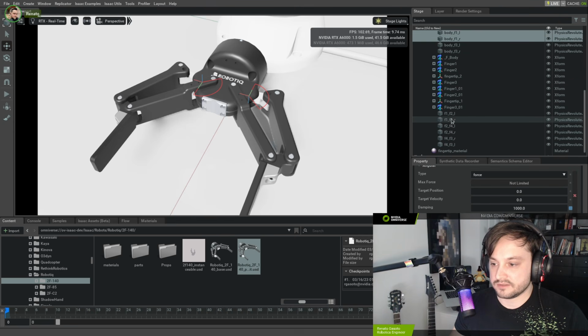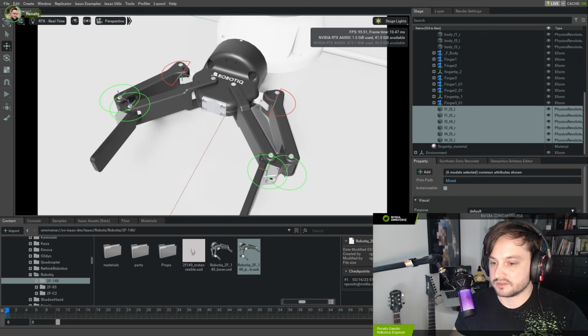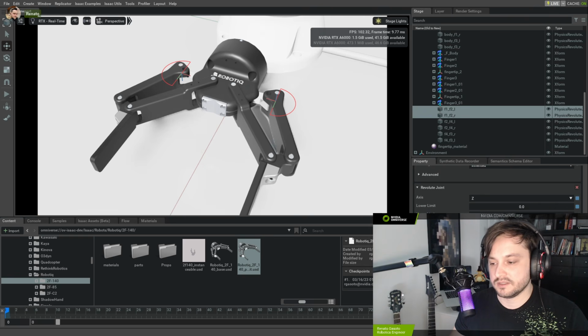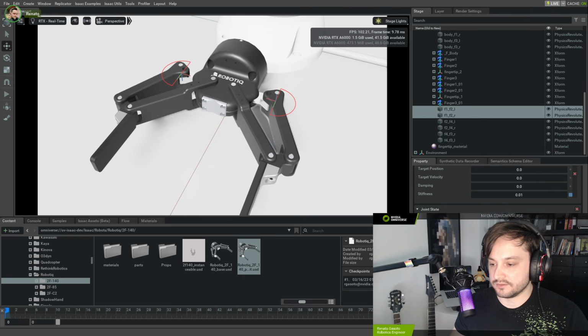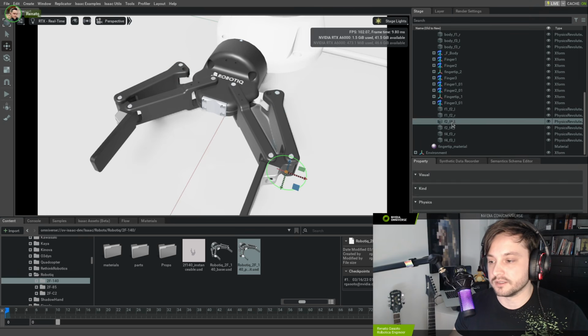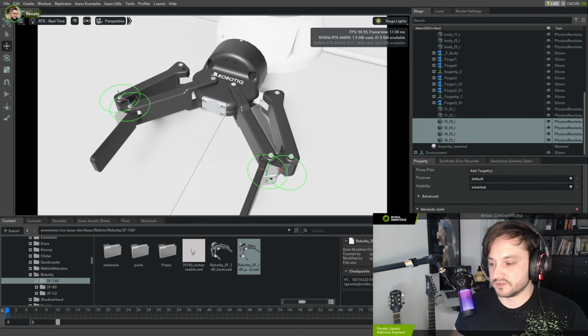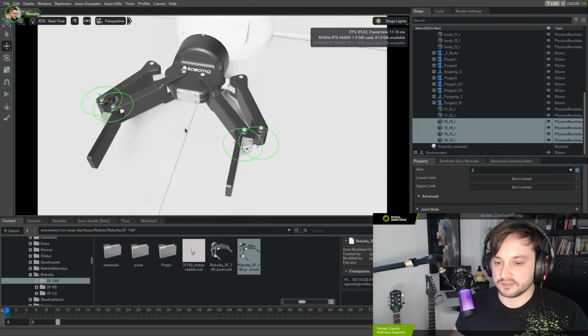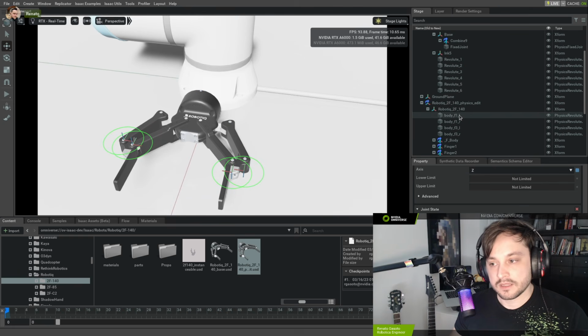And that was it. Everything else here, if you go to the other joints, I set some limits to those two joints as well. Okay, I forgot about those. Yeah, those two joints, they also have limits, but they don't have drives. They have just a small stiffness to make sure that they comply better. But all these other joints, they're just open joints. They're limited by the rest of the hierarchy of this gripper.